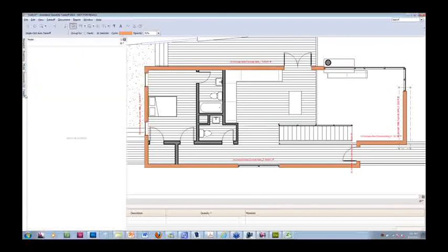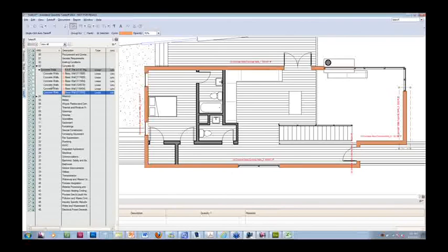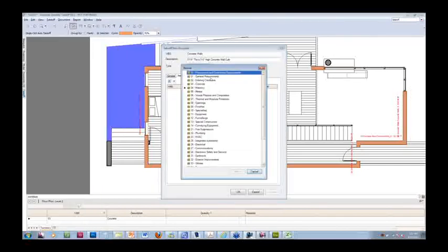And watch. Now, just make sure that you don't move your mouse around because it just makes it disappear. Now look at this. I have all my walls listed here on that pull down with all the ones that I've selected, and because they come with all this information about their height, the thickness, and so forth, you can reuse that parameter for adding formulas to it if you wanted to. So for instance, if I go back to my properties here, I could use an assembly that would be based, let's say, for this, the one for concrete right here.